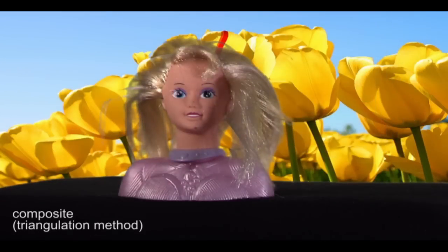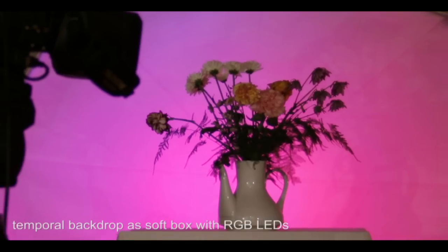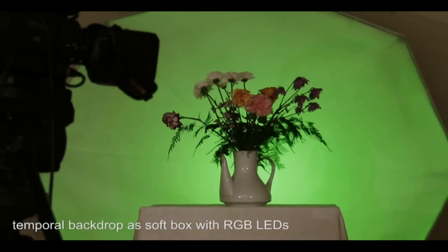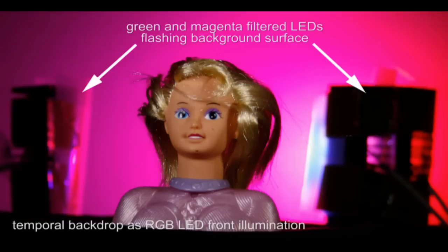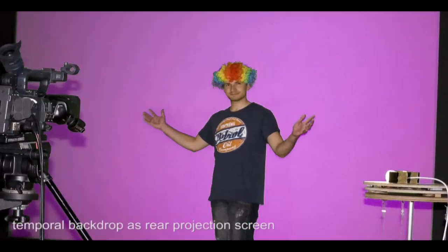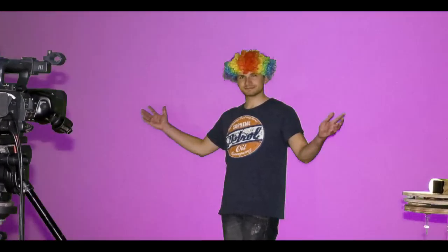For synchronizing the temporal backdrops with the shutter of the camera, we utilize the camera's composite output signal as an external trigger. We implemented different prototypes of temporal backdrops: a softbox with integrated RGB LEDs, a RGB front illumination of a diffuse background surface, and a back projection screen. The foregrounds are lit with arbitrarily aligned spotlights.